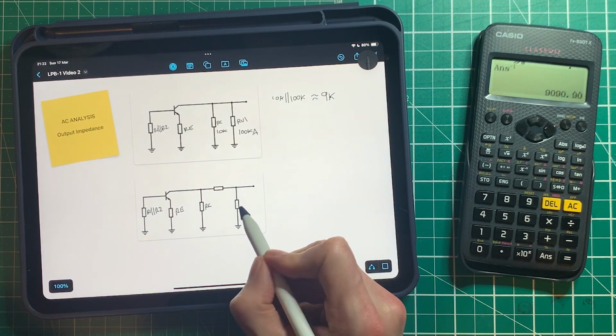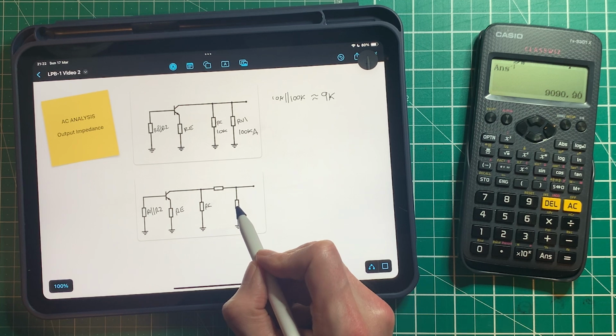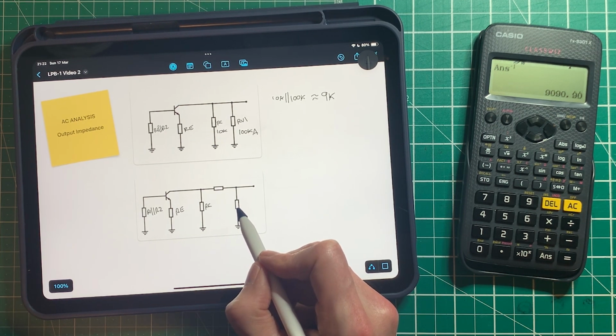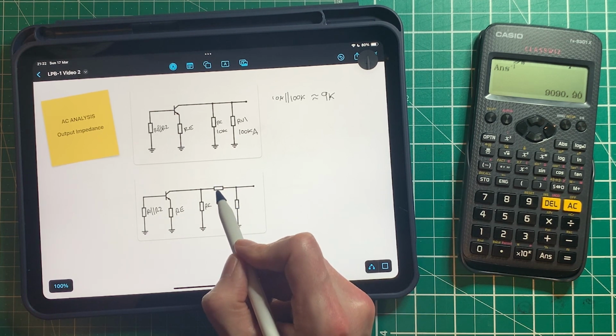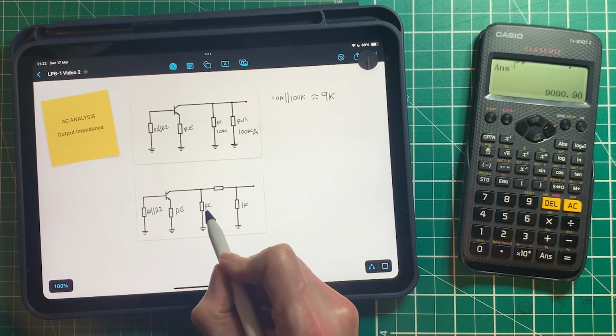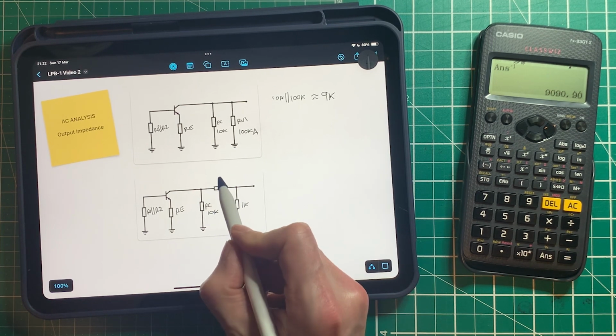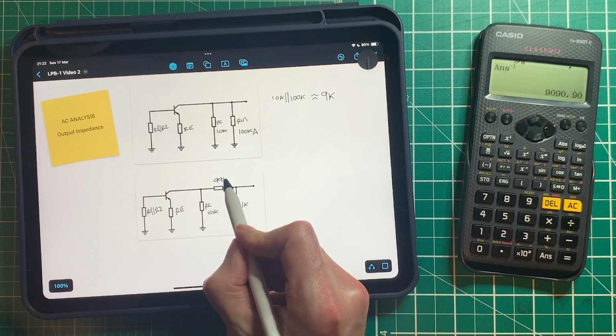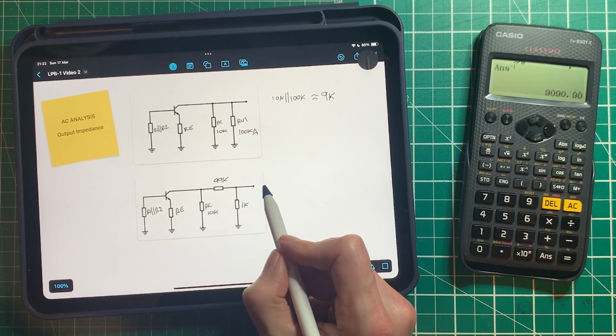Here, I've put in a little bit of resistance here because obviously it's going to go down to 0, but it's not actually going to get to 0 in reality. So let's say this is kind of 99% of the way there instead, and that's going to put 1K there. This is 10K, of course, and then the other 99K is here. So let's just calculate for that.